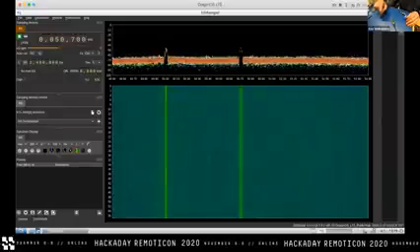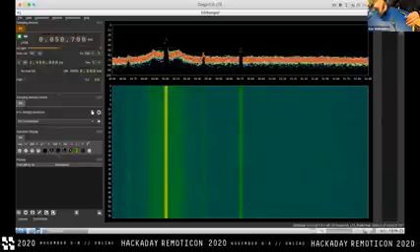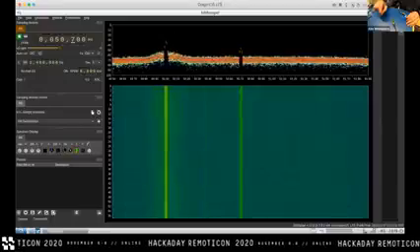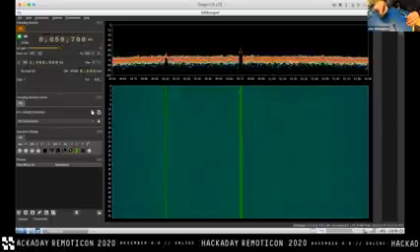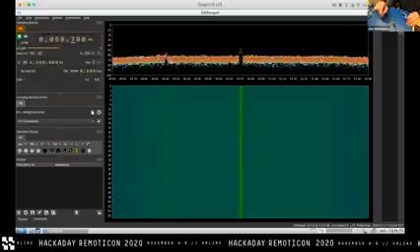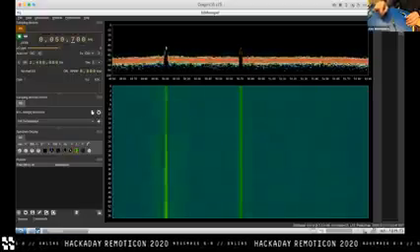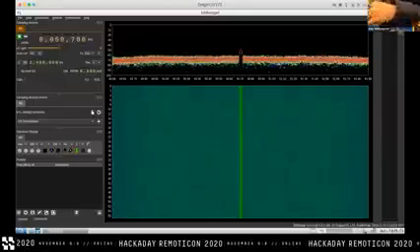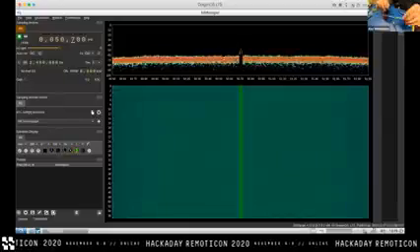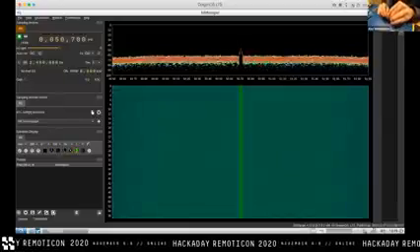So it's probably not this SPI flash device. It might be the FPGA itself, but I'm not really sure. It's probably not the USB because 50 megahertz doesn't make a ton of sense. And obviously, as soon as we get up the cable, the shielding, no, it's definitely not that. So it's somewhere around here. Obviously, you already know where it is because I told you I pumped a 50 megahertz signal out to the LED, but let's just verify that.